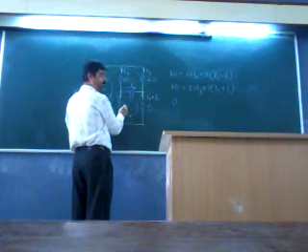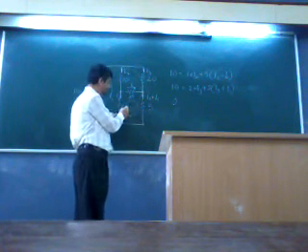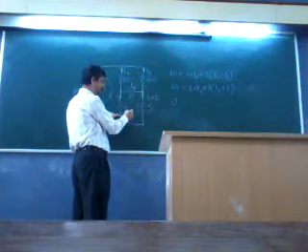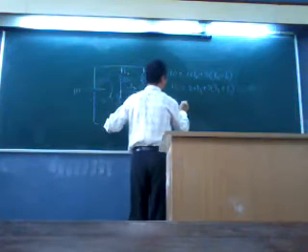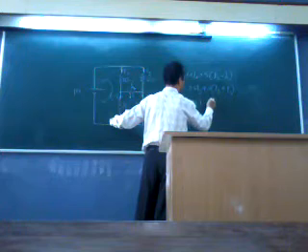Current is I2 minus I1 into 5, but in which way? It will be minus because you are traveling this way and the current is in this way. I2 minus I1 is assumed in this way and you are traveling in reverse. So 0 is equal to minus into bracket 5 I2 minus I1.